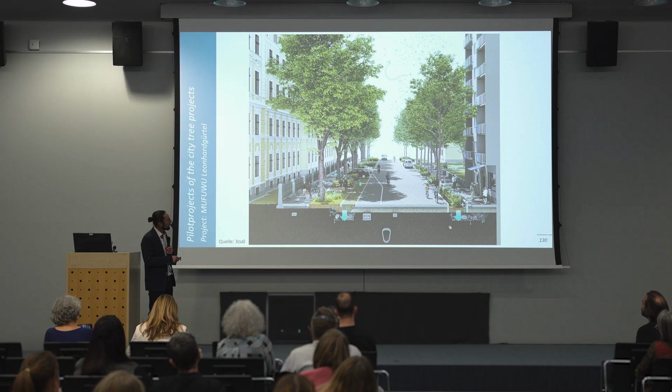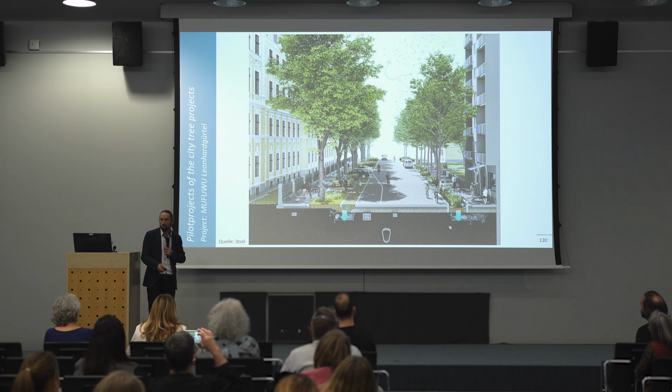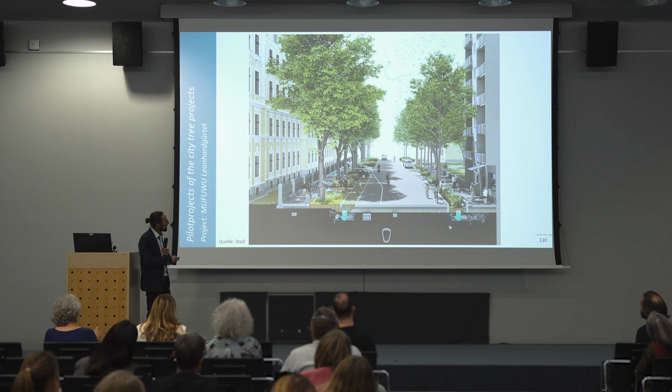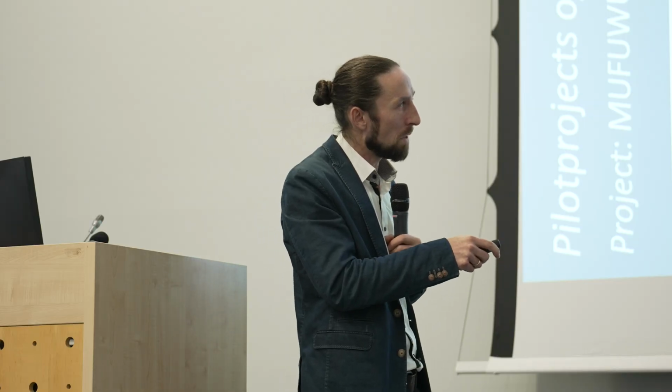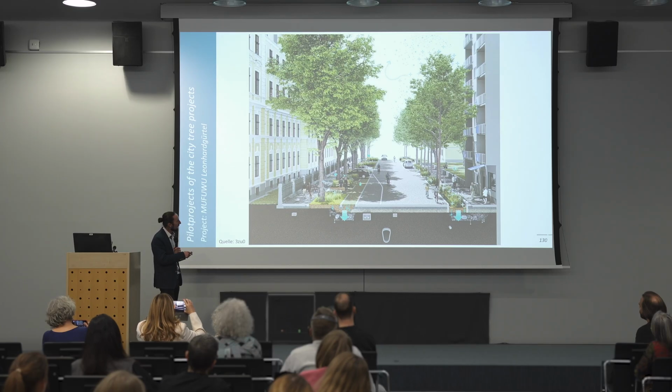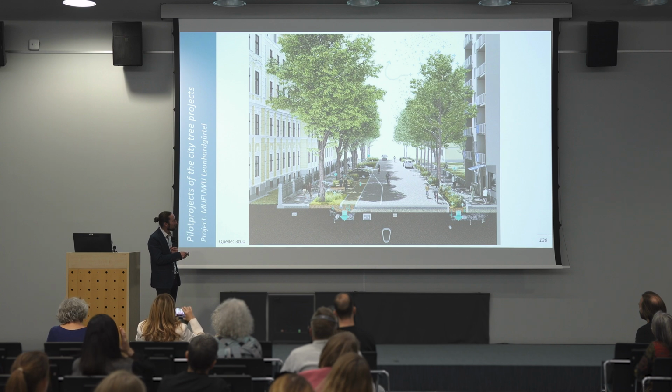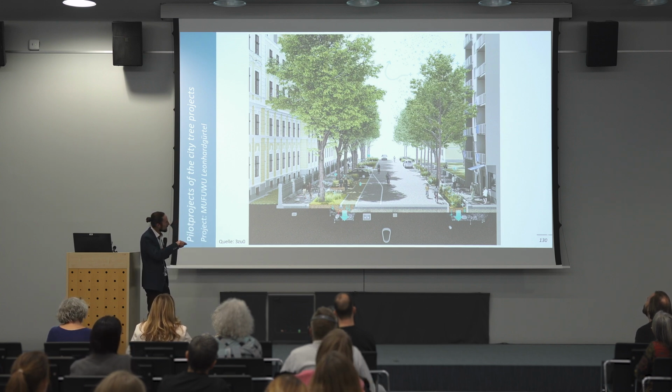This means that we infiltrate the water from the street through a planting pit with perennials. So you have kind of a filter. Then we have the infiltration of the water through this permeable parking surface. And we infiltrate the water from the pedestrian area directly into the underground. And there's this structural soil in one line on both sides. And we also put some of the roof water into the system.